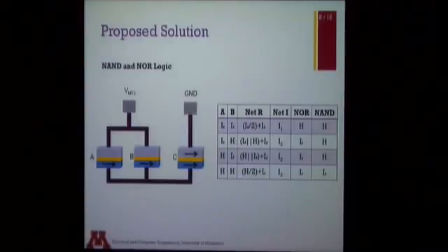The resistance in this particular circuit is here. So the first term is the parallel resistance of the input MTJs, and the second term is the preset low resistance of this output MTJ. So A and B are input, C is the output. When we apply a voltage at this terminal and ground this particular terminal, then there's a current that flows through this circuit. So let's suppose the currents that are flowing are I1, I2, and I3.